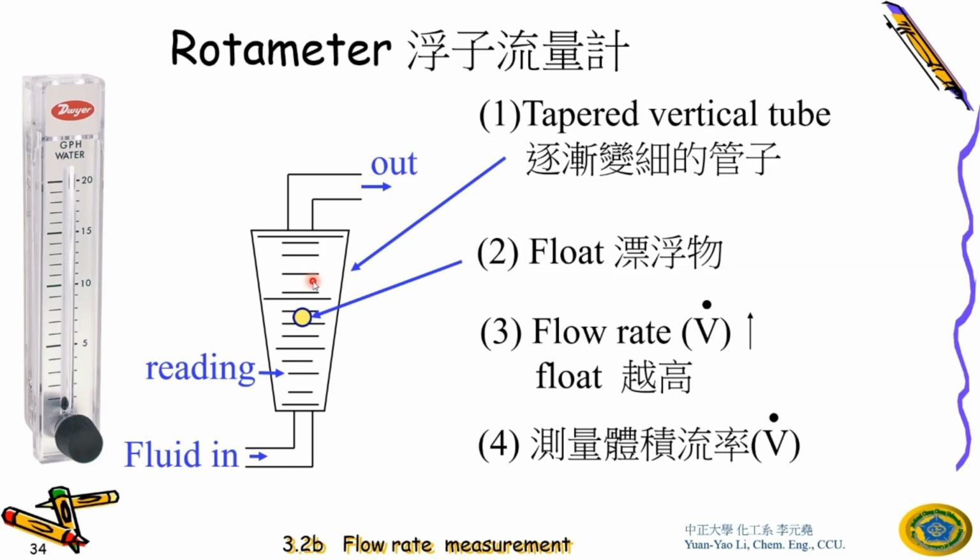And the important thing is: does this measure the mass flow rate or the volumetric flow rate? I hope you remember, on Monday I showed you a video, right? We counted the volumes during the calibration, right? So a value of 50 milliliters. So we are measuring the volume. So this is measuring the volumetric flow rate. I want you to tell me this full information in your midterm, in the midterm celebration of learning.